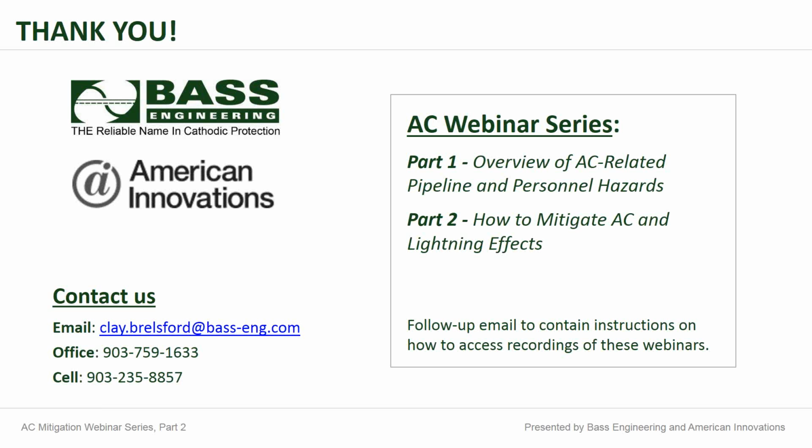Thanks. For the next question, when using an SSD with a gradient control mat, do you take into account the CP voltage of the pipeline or the CP voltage of the gradient control mat for the proper SSD? Again, these are great questions. The overall potential will be a mixed potential, because your gradient control mat is essentially going to exist at something around negative 1100 millivolts, because it is zinc. But it's going to have imperfections on it. You're going to have some bare steel exposed and things of that nature.